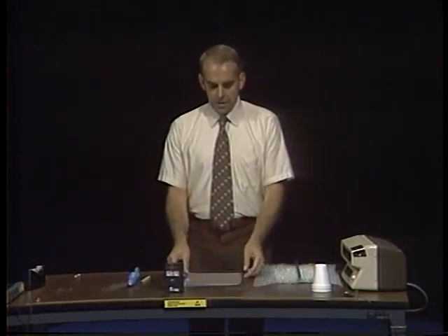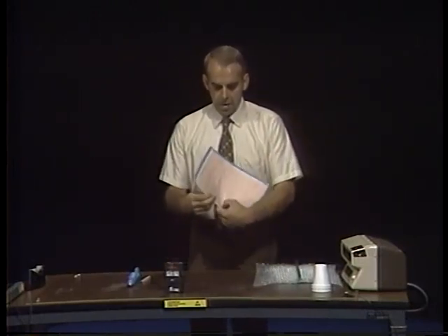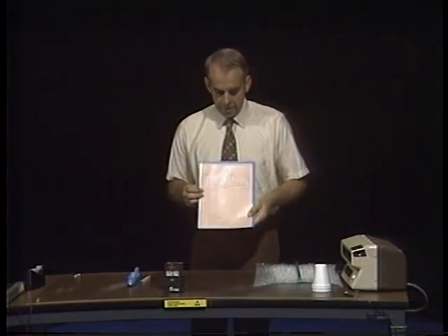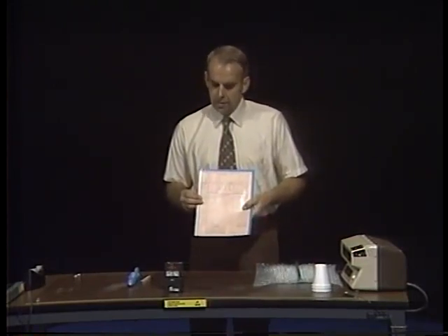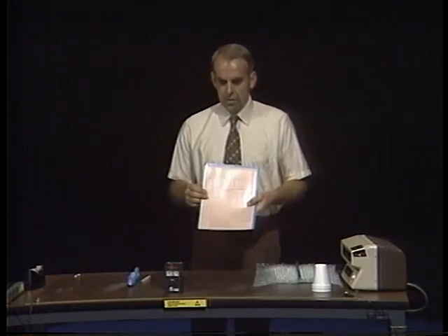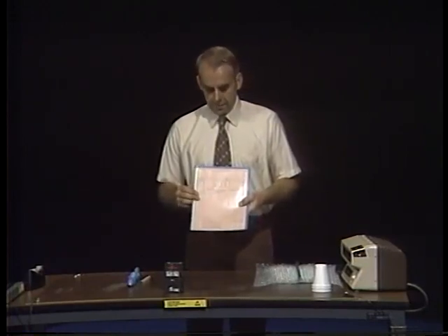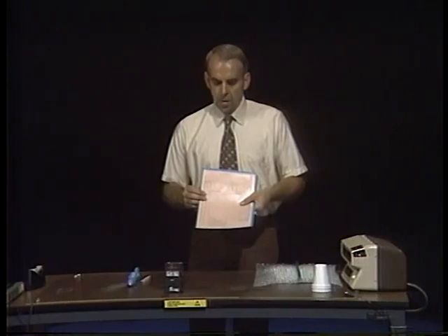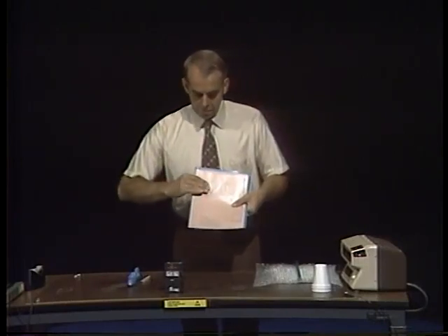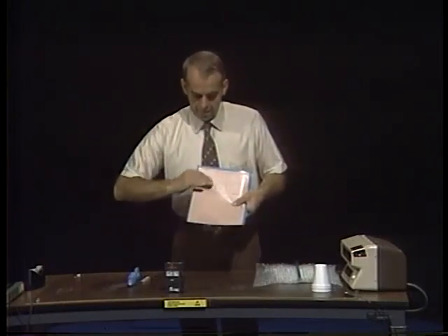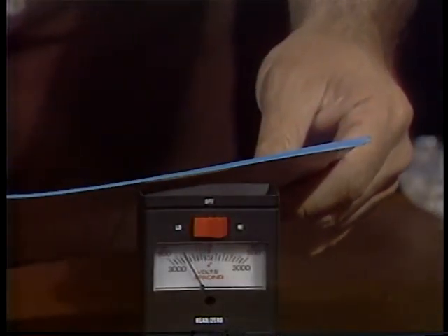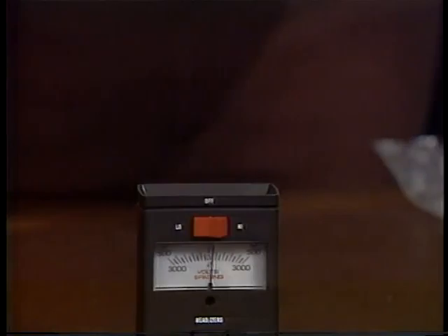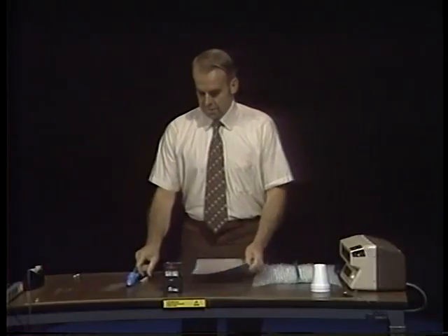One sneaky killer of electronic circuitry is the vinyl work order traveler, an example of which is shown here. These vinyl travelers can be charged up by handling, and should they be placed on or near a circuit, damage could result. Let me illustrate. As you can see, there is enough charge there to do damage.